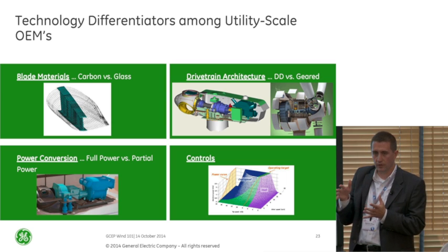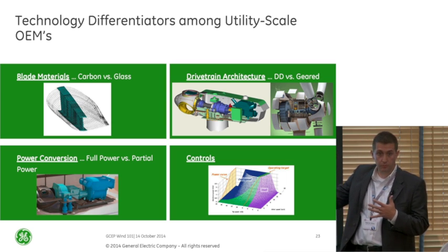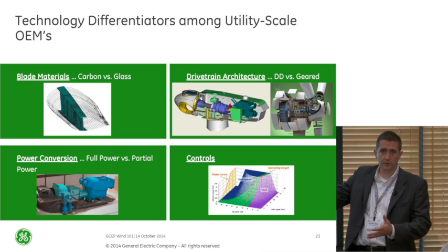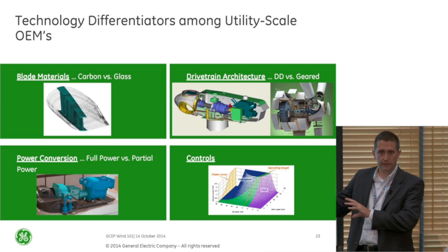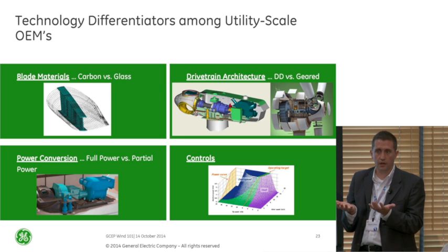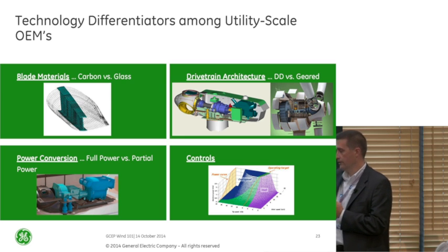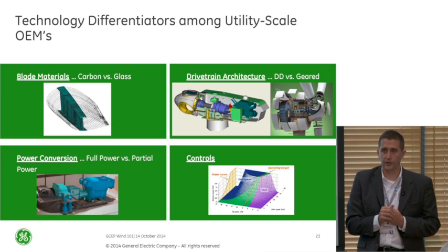If I wanted to make this blade really stiff, typically what's done historically is you just make these fiberglass I-beams, right? The one idea is I could take a heck of a lot of weight and cost out of my blades if I moved to carbon fiber, right? Because it's a lot lighter, very, very stiff. I don't have to use as much. The problem is you now have to balance that against the added cost. And now you have introduced a new material that you need to go through the whole O&M perspective on as well, in terms of how do you make sure that it lasts accordingly.